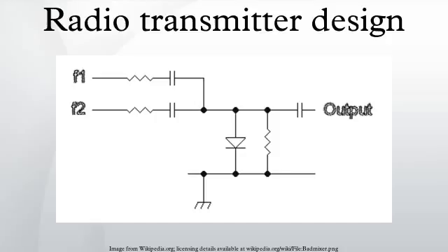Spurious emissions. Early in the development of radio technology, it was recognized that the signals emitted by transmitters had to be pure. Spark gap transmitters were outlawed once better technology was available, as they give an output which is very wide in terms of frequency. The term spurious emissions refers to any signal which comes out of a transmitter other than the wanted signal. In modern equipment there are three main types of spurious emissions: harmonics, out-of-band mixer products which are not fully suppressed, and leakage from the local oscillator and other systems within the transmitter.